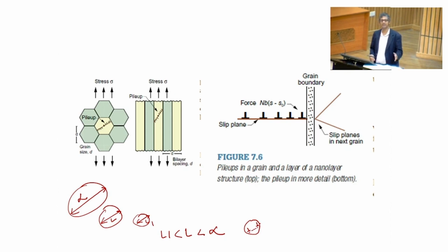And when 2 persons are standing in front of a ticket counter, they can peacefully stand far apart from each other without applying force on each other. There will be no pile up, there will be no stress acting on the grain boundaries. If no stress is acting on the grain boundaries, its action as an obstacle doesn't make any sense, okay?